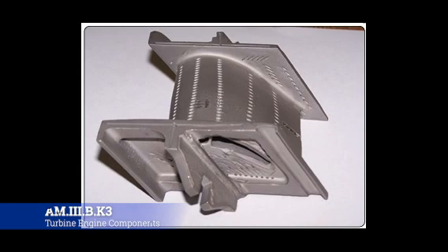So whenever we start talking about potential engine problems and failures, like hot starts, think about it: if you go over EGT for too long, you're going to overheat these things, cause them to expand, warp, or whatever, and it won't work properly after that. Or the worst case scenario, you have a catastrophic engine failure, and that might happen later on.